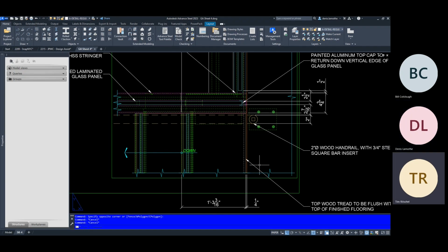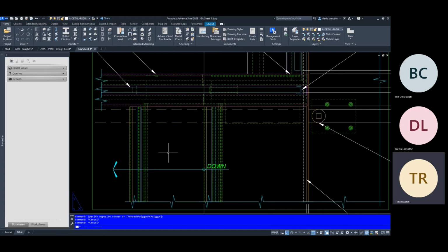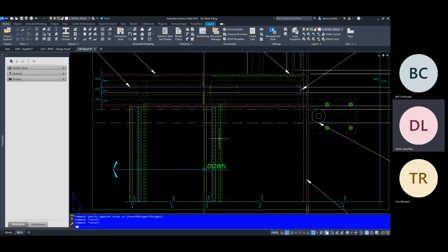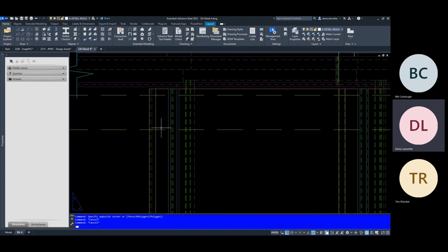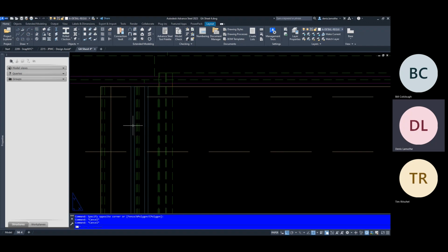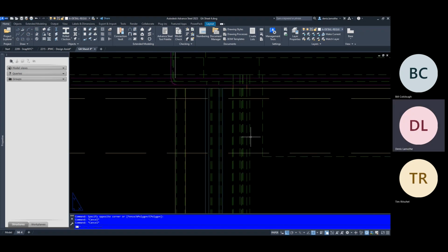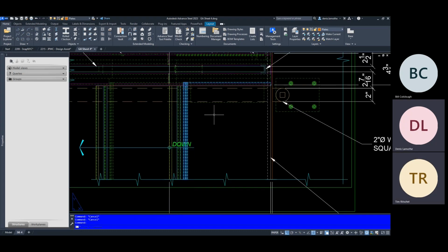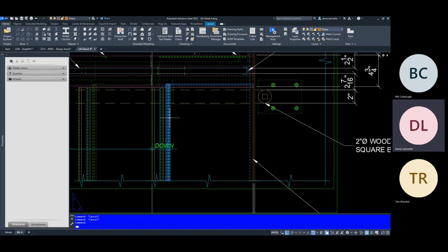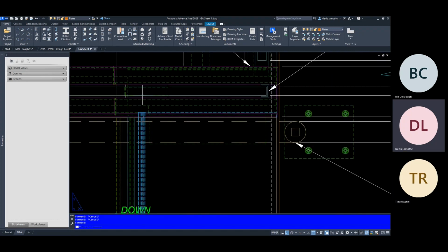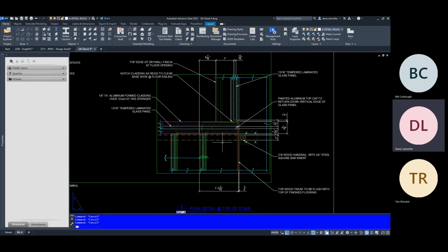That's one reason why I liked SolidWorks. When I was doing my detailing and drawing layouts, if I had too many hatch lines and stuff that wasn't pertinent, I could right click or click on it and then hide the specific line. And Autodesk Inventor does the same thing. You could click on just the one line and hide it. Like in this case, I'd be doing that frequently because there's a whole bunch of these hidden lines I don't want to see. But yeah, you had that ability. Advanced Steel, however, that line is attached to the entire part, right? So you delete the one line, you're deleting everything, even the ones that are supposed to be visible. So yeah, a little harder to work with.